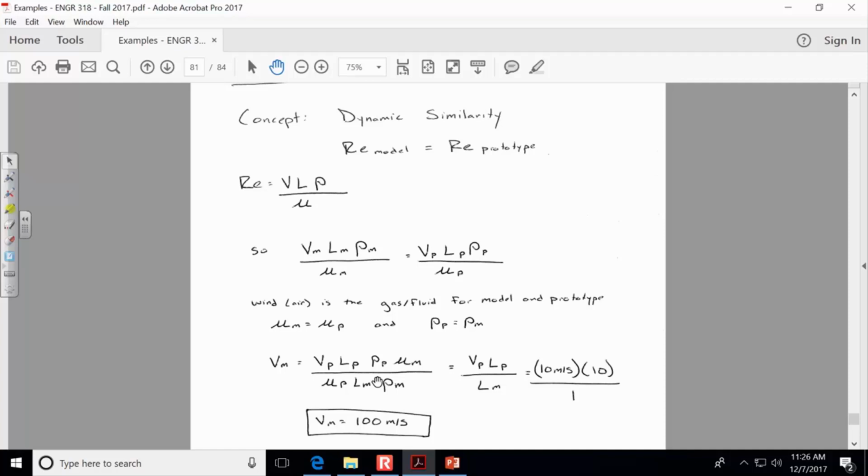And so the way to think about that, remember I said in the case of the Matchbox car, the little Matchbox car is too strong relative to its size. And so if you want to simulate a crash, you have to give it much heavier forces on the small model. And so in this, the analogy is that since it's smaller, it's going to be more rigid, less likely to deform under the winds of 10 meters per second. So you'd have to give it 100 meters per second to maintain that same Reynolds number proportionality. Any questions about this first example?